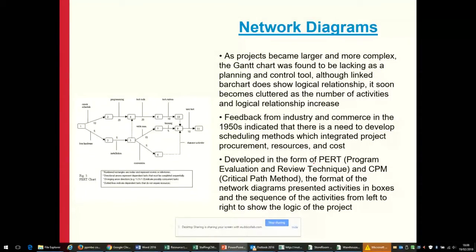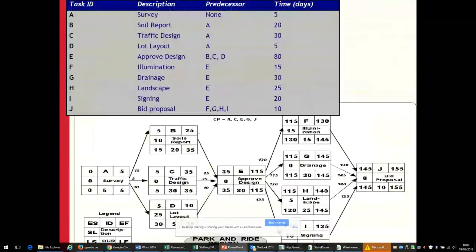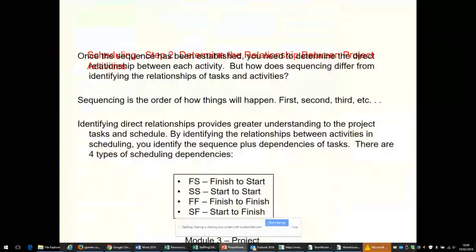In our previous examples, we did review the PERT, or program evaluation and review technique. So it is in contrast to deterministic scheduling. Very often we are working with time brackets. So work on any activity could take anywhere between 5 to 9 months. In those circumstances, we take a pessimistic time, an optimistic time and the most likely time, and the CPM scheduling. So we did this example, and we learned how to convert a method statement into a clearly laid out network diagram with clearly laid out relationships. And just a reminder, we did an example like this.